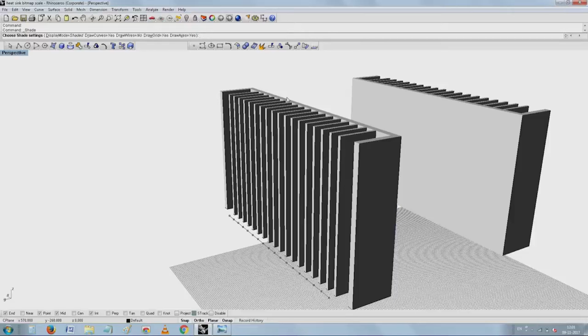the other proportions. If it is a rack mounted equipment, usually the front is a 19-inch panel. Inside, what goes inside is, if you take 426 as the width, 19 inch as the width, usually if you leave 20 for the flanges, remaining happily goes inside the rack. These standards you need to verify, you should not take it from me. So, if you verify the standards, you will know the width.